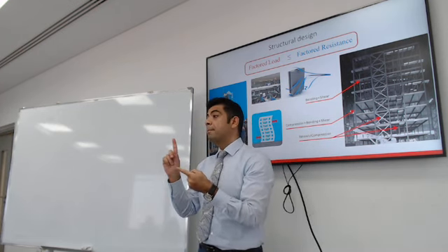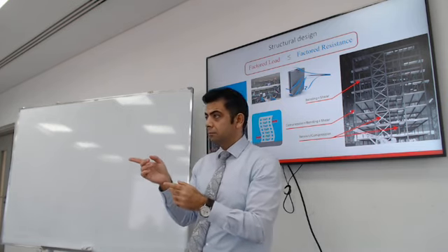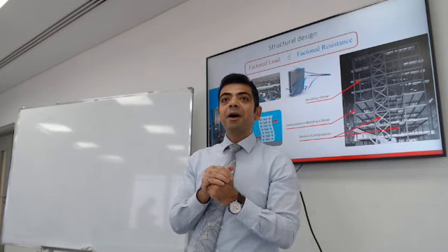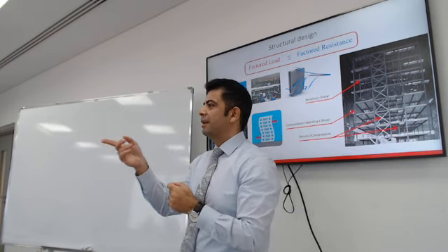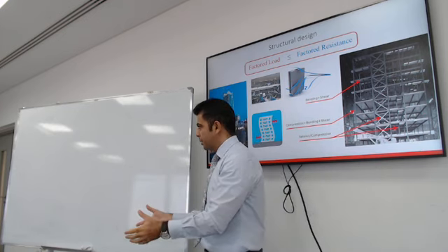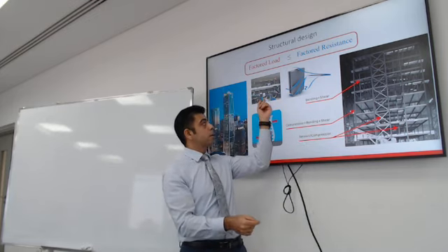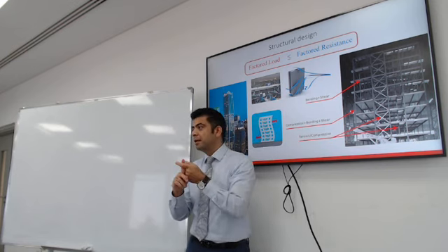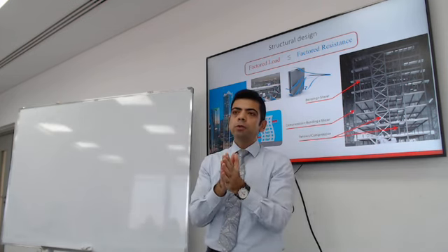How do you figure out the magnitude? How much is the live load on a building? Any other thoughts? How do we figure out the live load on a building? I need you to think about this one. Use of the building. How it's going to be used, is it residential, commercial? Yes, it depends on the use of the building, and then you reference the local codes, and it will tell you how much weight of users of the building you should use. Perfect. So once you get the load on the building, what do we do next?